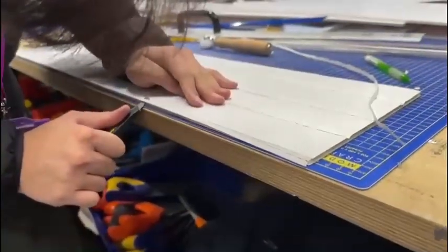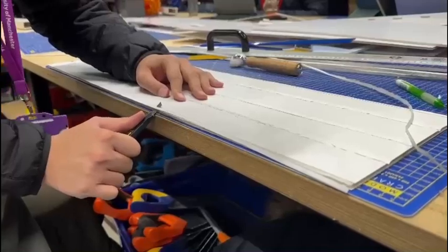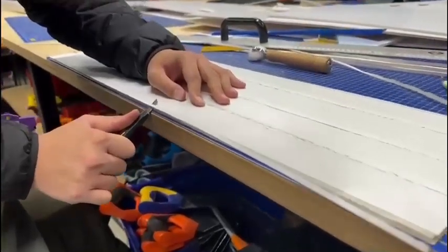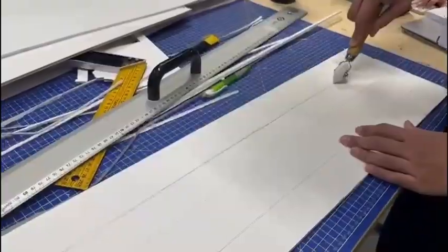The deflection was recorded and the angle due to deflection was calculated. The bending experiment used a similar setup, but this time the masses were added to the beam's tip. The deflection of the beam tip was recorded as each increment of the mass was added. Thankfully, our design passed both tests and we can now move on to mass reduction.